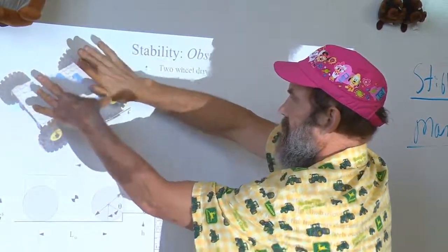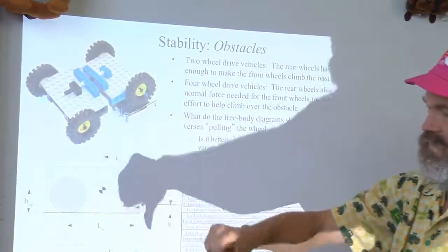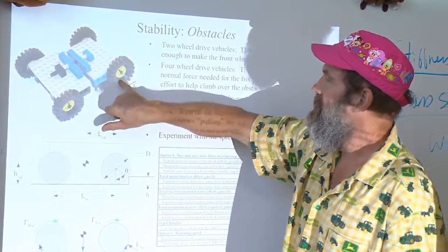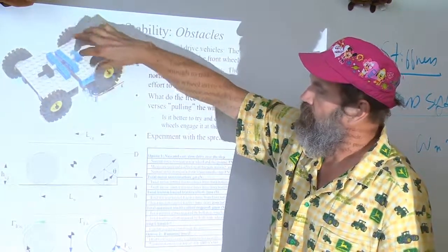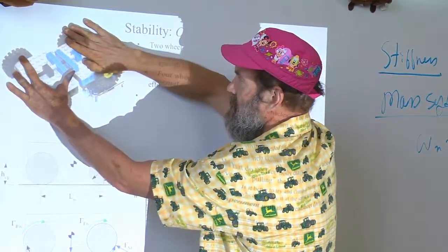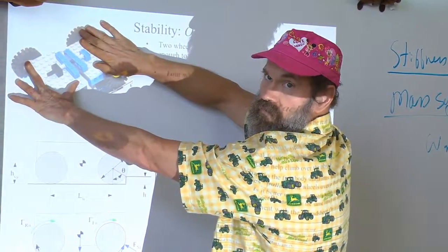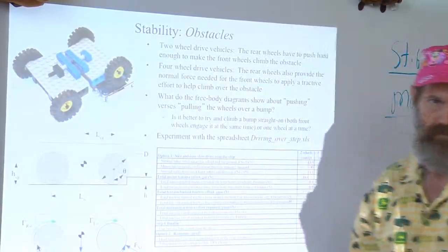So the front and the back can pivot with respect to each other. The pivot is then designed to be strong in bending, and now I can accommodate varying ground, and this pivot between the front and the back of the structure makes the vehicle emulate as if it was a three-wheeled vehicle, yet have the stability of a four-wheeled vehicle.